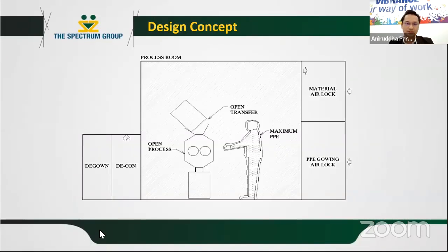Then these are some of the various design concepts as we look to select a specific solution. There is typically an open transfer, open process. You can still do this, but then you need to have complete maximum PPE, the Tyvek suits and all. And as you can see in the indicative drawing, you need a PPE gowning airlock to come into the area. When exiting the area, you need to use a mist shower, decontaminate yourself, degown, and then get out of the area. So this is a very simple method, but not